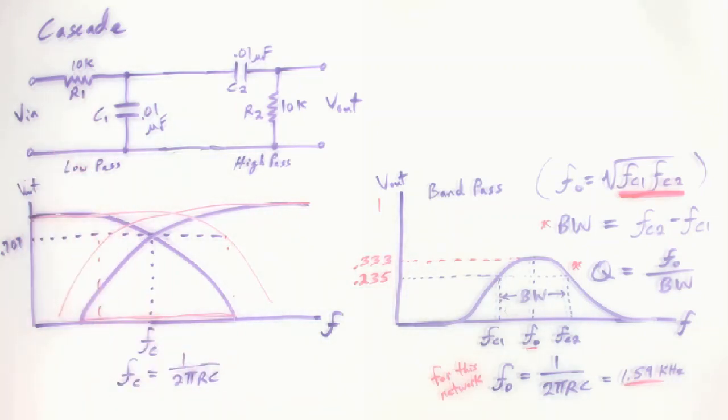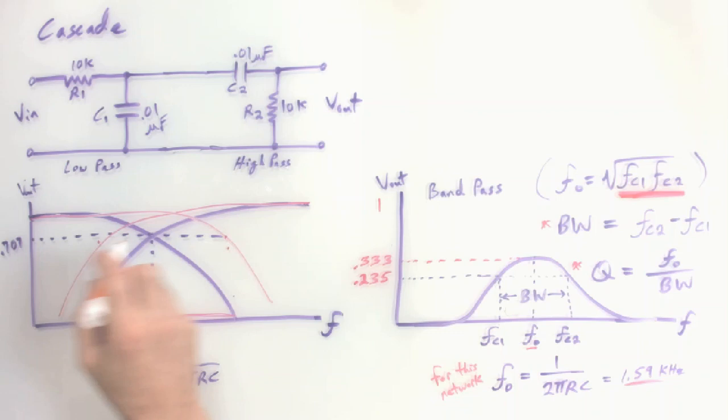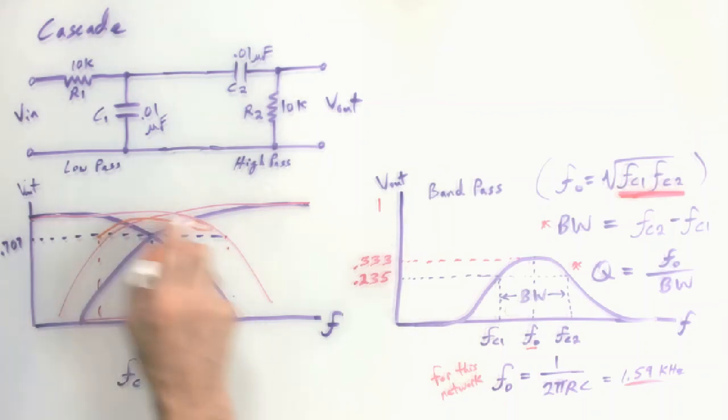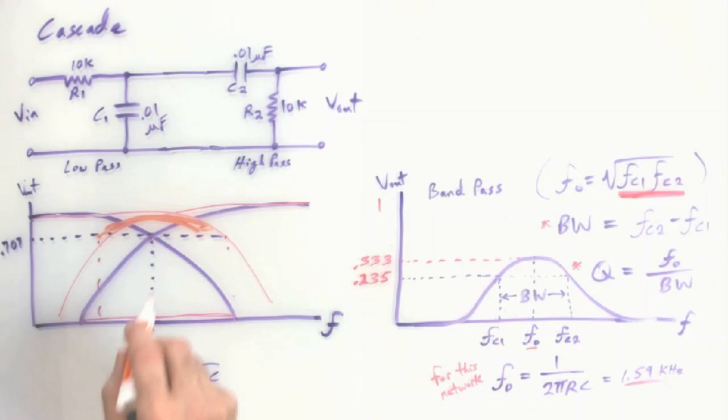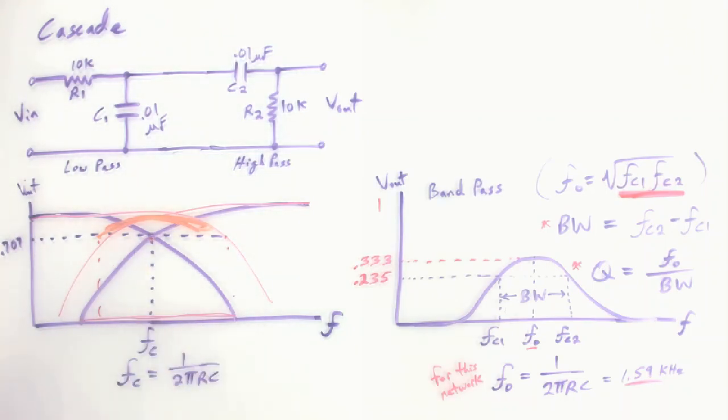If you're doing a single pole design like these, you might not use the same component values. And what that does is give you a little more overlap for your filter. I mean, you can see here, I have sort of all this area now to work with, instead of just a little bit of one frequency that they had in common. So, now that I've totally messed up that drawing, my intent is to use this as an introduction to bandpass filters in general as well. So that's why we went through all that.